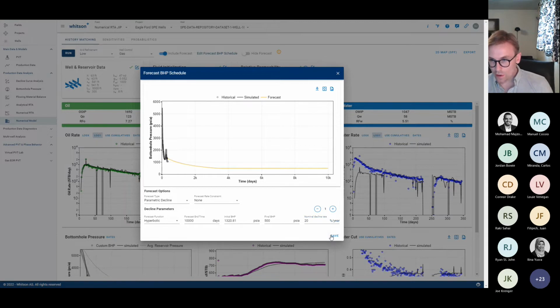So that's a great question from Amy. Are most people using BHP control when they have gauge data, and gas oil rate when they don't? I think that's a good way to summarize it. Like, if you actually have measured gauge data and you have a very big certainty in that data that is also correctly converted down to sandface phase, there's probably no reason to assume that is a wrong measurement. So that's my general observation as well.